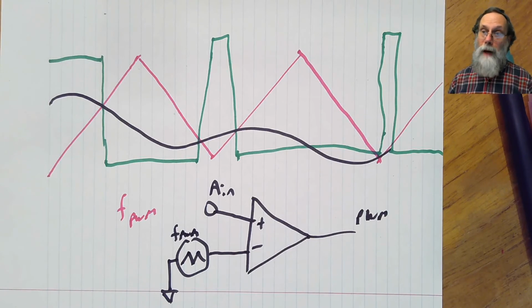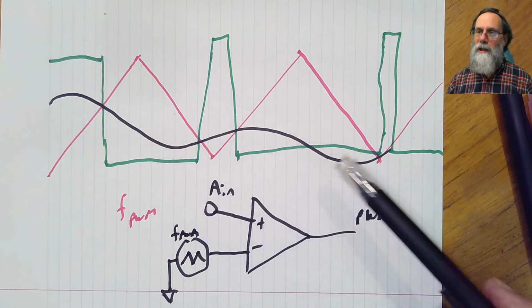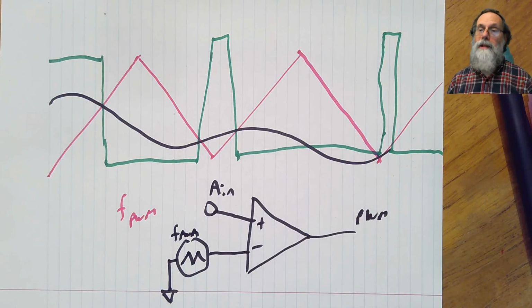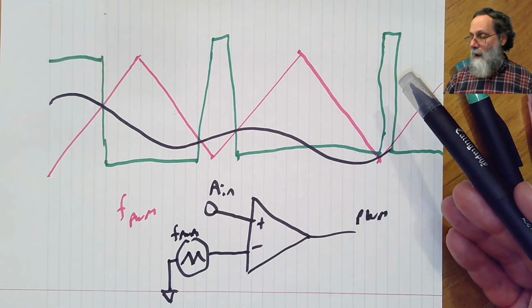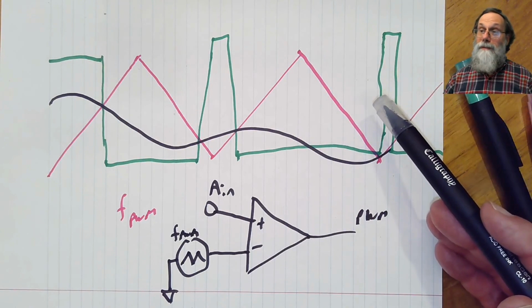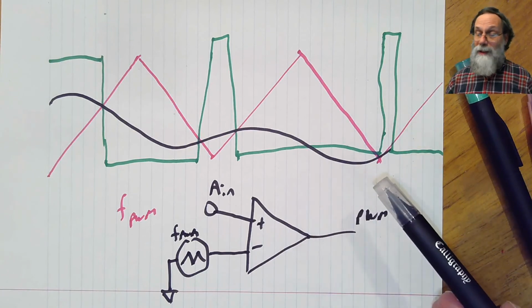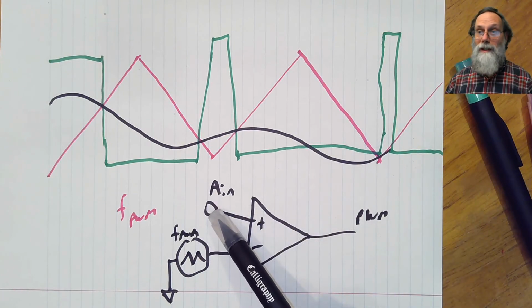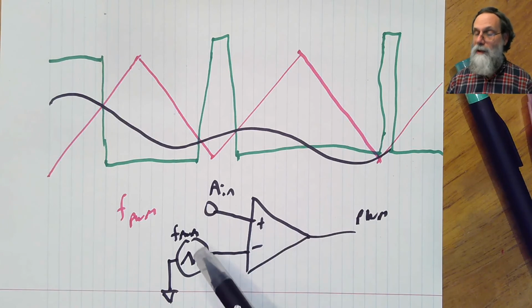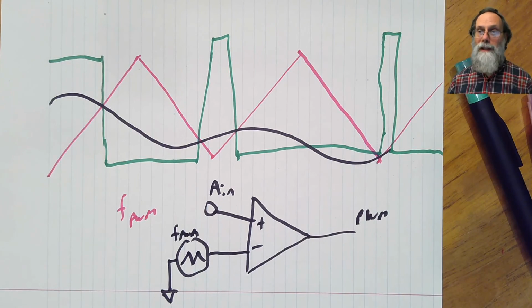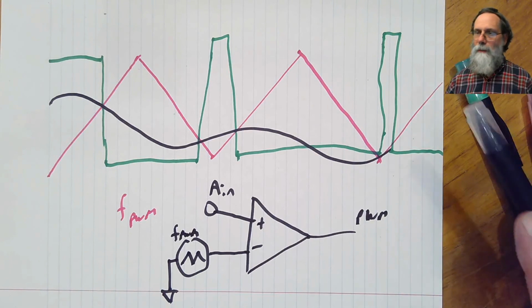Generally, for what we'll be doing in the power amplifier, we'll want to have a fairly large variation in the duty cycle possible, because that will give us the largest variation in loudness of our signal out of the loudspeakers. But that may be too loud for a lot of applications, so for some of the times we'll be shrinking the analog input signal down to only a small piece of the voltage range of the triangle wave, getting a small fluctuation in duty cycle and a much quieter signal because of a smaller change in the effective signal to the loudspeaker.